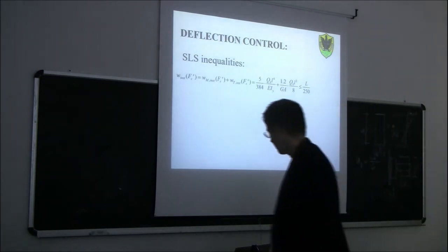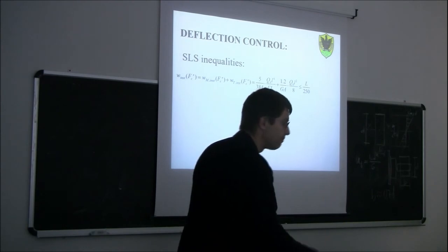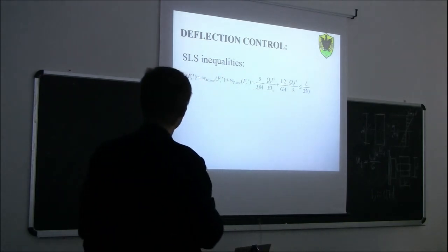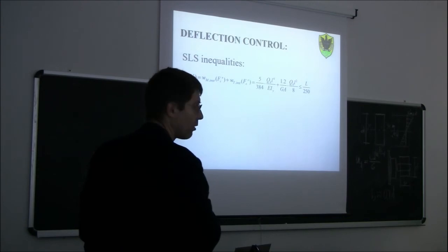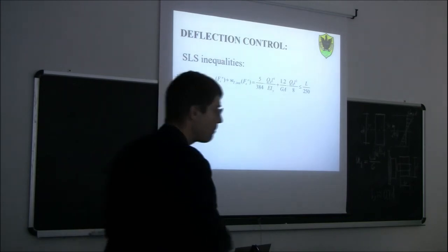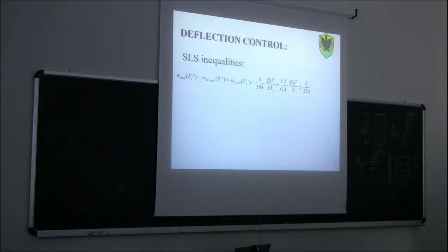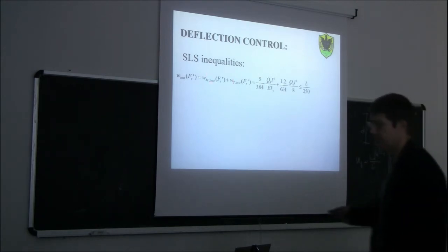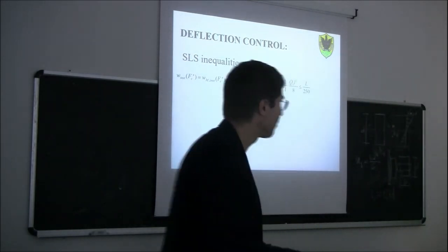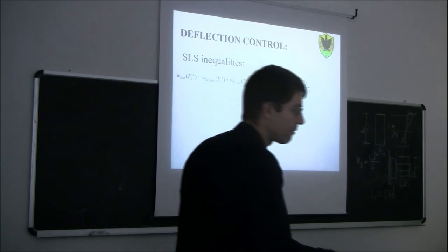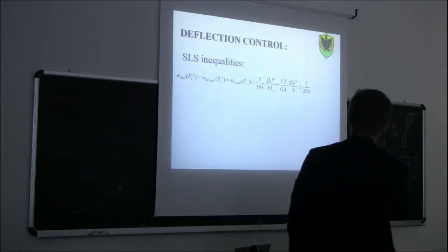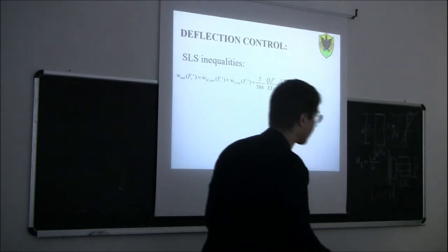So, if you look at the formula that we derived last week, the instantaneous deflection due to a certain load, Fc prime, you remember, unlike what we were used to do for reinforced concrete, or for steel, actually for steel we haven't done anything so far, we'll do it probably next year, you need to remember that also the shear component of the deflection is important. So we need to add the shear component of the deflection to the bending component of the deflection, the one that you are used to consider in structural mechanics.